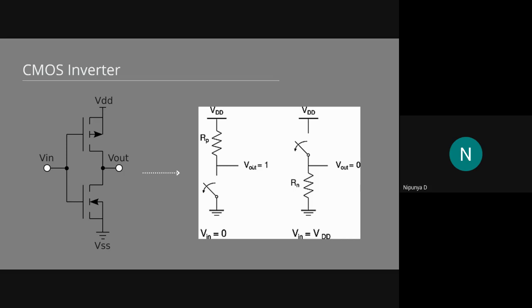Whereas when you apply the input voltage the same as the drain voltage, the NMOS transistor will conduct, whereas the PMOS transistor doesn't conduct and hence acts like an open switch, because of which there is no flow of current and hence voltage, so your output will be 0. So this is how exactly it matches with what we know when we dealt with digital circuits as well. So now let's get started and let's build it quite quickly, since it's quite a simple circuit.